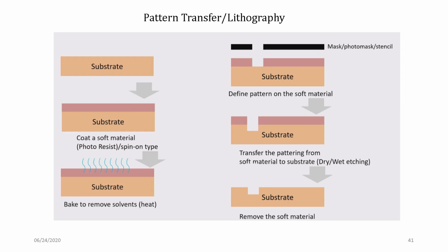It has to be heated, and then we have a mask. If it is kept at a farther distance, then we use Fraunhofer diffraction, which is projection for the photolithography. But mostly after this slide I'll be talking about contact lithography. We'll be only dealing with the masks which are kept in proximity to the substrate.